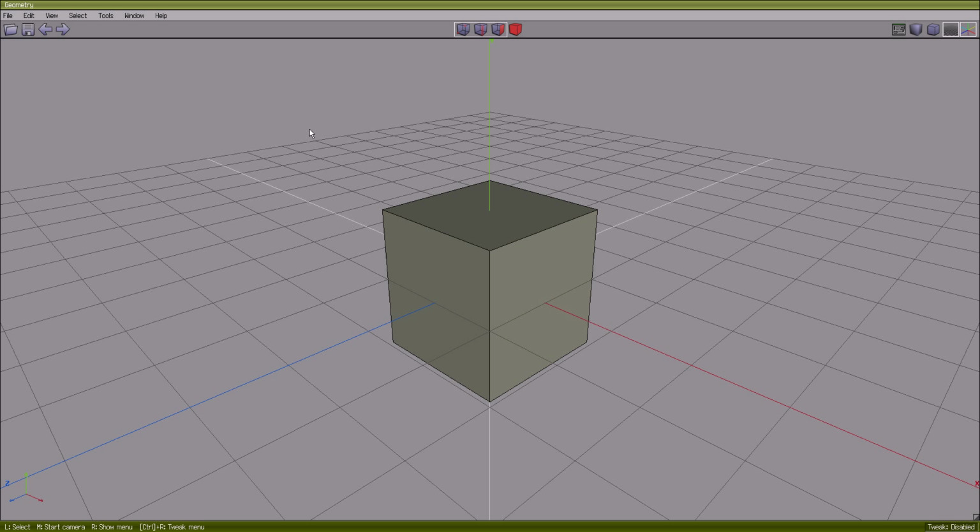Now we have to be able to navigate around this object. It's what is called the camera. Here at the info line you have the camera instructions. I am forgetting an important point. If you select a face, here you have the information about the selected face: its number, its coordinates, its material, and its area. Same for vertices. Vertices 1, 2, 5, 6 are selected.